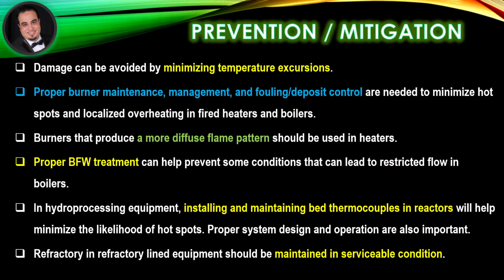Prevention, mitigation. Damage can be avoided by minimizing temperature excursions. Proper burner maintenance, management, and fouling and deposit control are needed to minimize hotspots and localized overheating in fired heaters and boilers. Burners that produce a more diffuse flame pattern should be used in heaters. Proper boiler feed water treatment can help prevent some conditions that can lead to restricted flow in boilers.